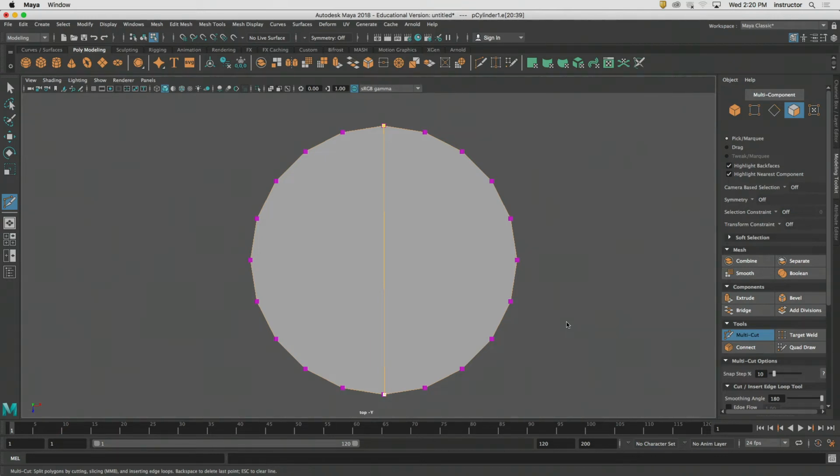When it comes to working with cylinders inside of Maya, or any app for that matter, we have to be very aware of the pattern that we're creating. Ultimately, what we're after is what's called a quad disc at the top of our cylinders. We don't want triangulation at all in our meshes. So this is kind of part of our responsibility as 3D modelers to go through and remove these caps, okay, and build our own, okay? It's good practice. It's going to set your foundation in stone.